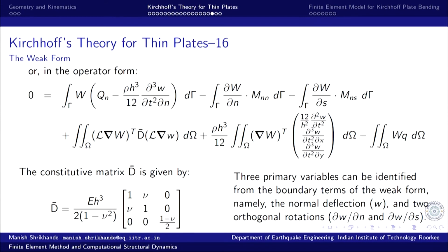In this case, of course, we need C1 continuity because the primary variables are the first derivatives. So, for C1 continuity, we have beam elements, cubic Hermitian polynomials along x, along y, multiply them. So, that was the first attempt at development of finite element model, but unfortunately that does not succeed.